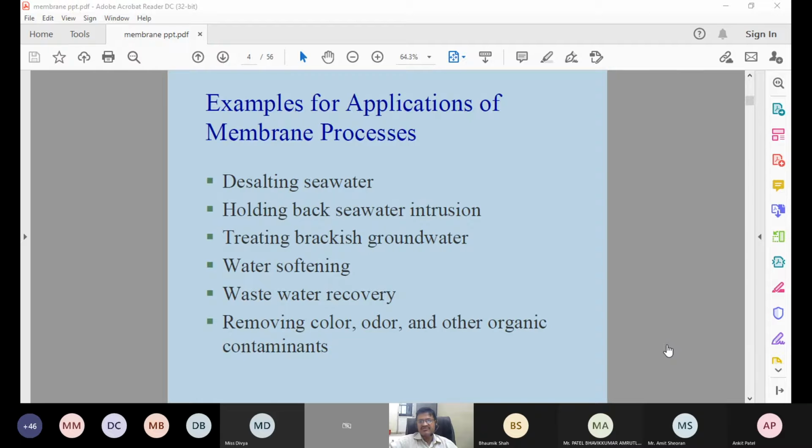How will we get the suspended solids? That is very easy. You filter the 100 ml, and whatever water you get in the beaker, just keep it in the oven. When this is evaporated, which type of solids will you get, suspended solids or dissolved solids, if anyone knows?